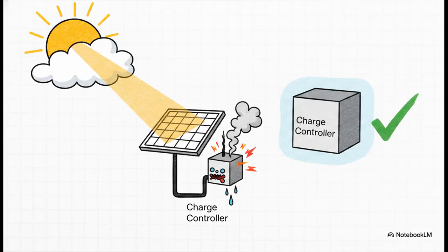But before we leave the math behind entirely, I have a quick question for you. Have you ever considered what happens when the edge of a passing cloud perfectly magnifies the sun? Yes, the cloud lens effect. It's a vital, and honestly often surprising, environmental derating metric. It causes sudden, localized solar irradiance to spike well past that standard 1,000 watts per square meter. To ensure your expensive maximum power point tracking charge controllers don't literally melt under these sudden thermal stresses, international electrical codes mandate a strict 1.25 safety multiplier on your continuous charge current. Bottom line, always oversize your regulators.